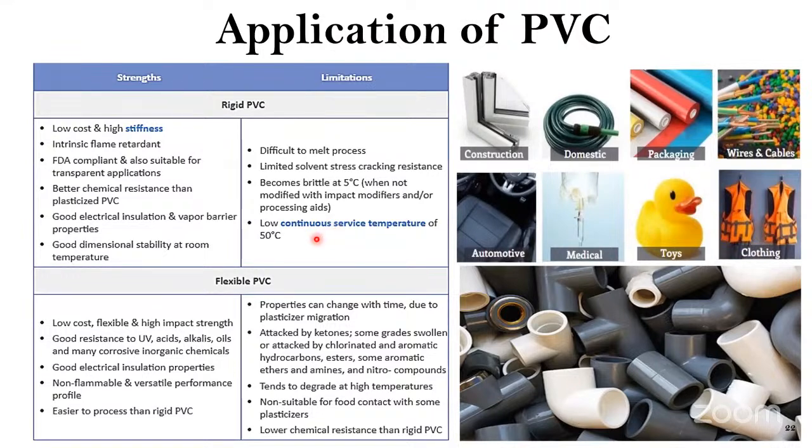You mean to say, let's suppose in injection molding, we are using PVC, then the temperature should be less than 50 degrees Celsius. Yeah, I'm talking about virgin rigid PVC. No additives, okay, I got it. You're talking about virgin rigid PVC. Yes. So then we can say the rigid pipe which is manufactured through an extruder is below 50 degrees Celsius only.